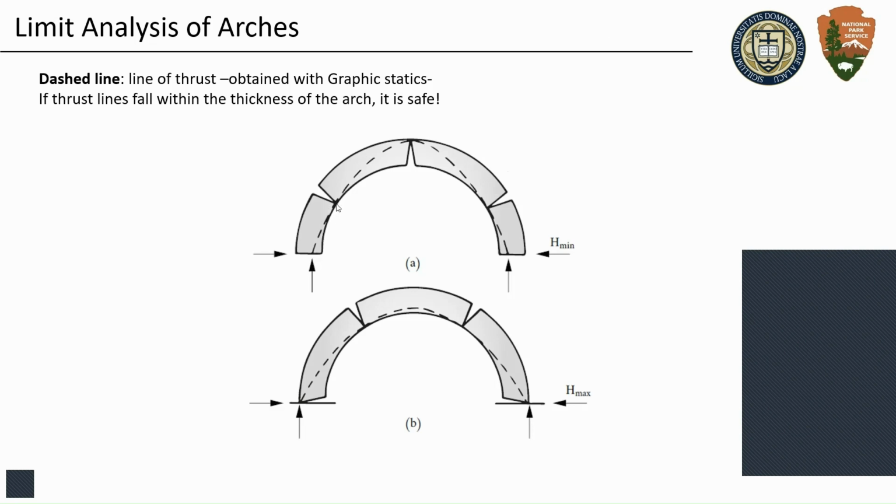So we may crack our arch, or we may have a compression thrust that is going around the edges of your arch, and that leads to compression on one end but tension in the opposite end. Or we may have this other scenario, but in any case, these are the points that will probably lead to the collapse of our arch.